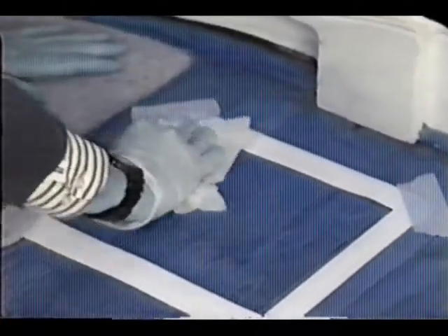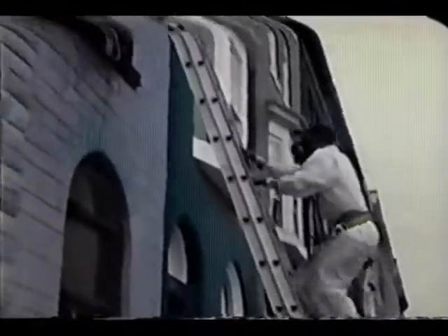There are 4 critical steps to any lead hazard control work: worksite preparation, hazard control, cleanup, and clearance. Lead hazard control methods generate varying amounts of leaded dust, paint chips, and other lead-contaminated materials. Each of the 4 steps must be conducted with the necessary precautions to protect residents, workers, and the environment.